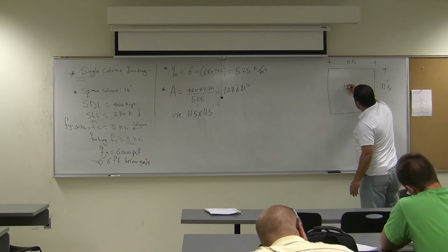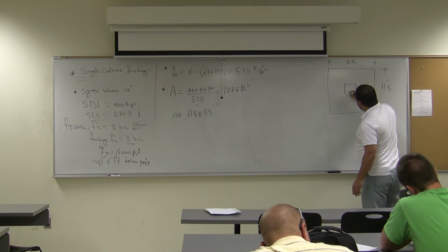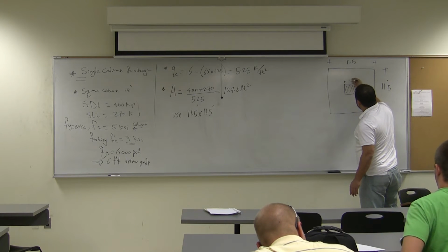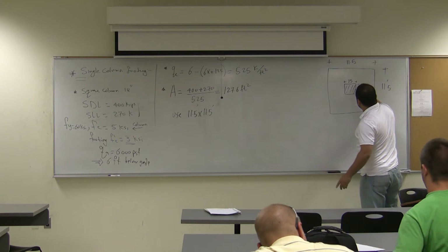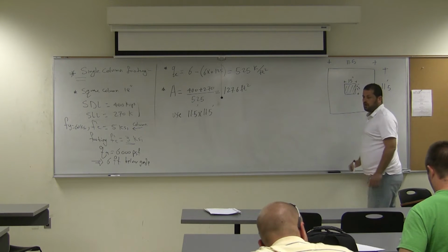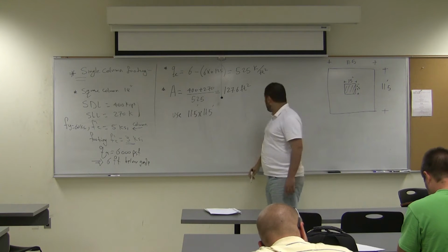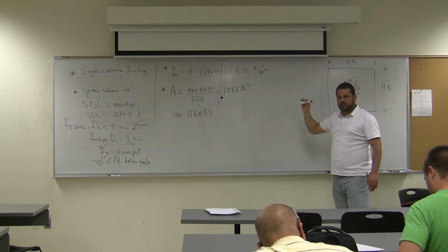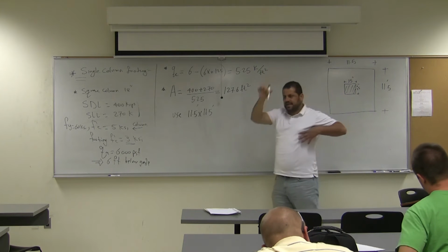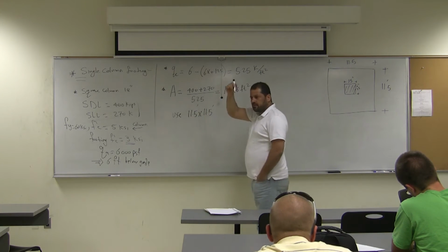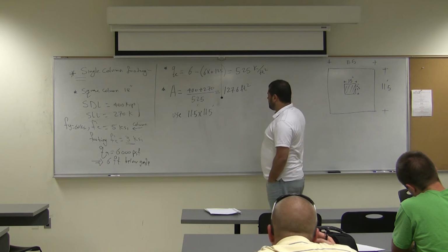11.5. And this is your column, which is 1.5 by 1.5, right? 18 inch is 1.5 foot. That's your column, 18 inch, 1.5 by 1.5, in the center. Again, the construction workers make sure it's exactly in the center. They take a lot of care when they put the center lines for the footings and the columns.